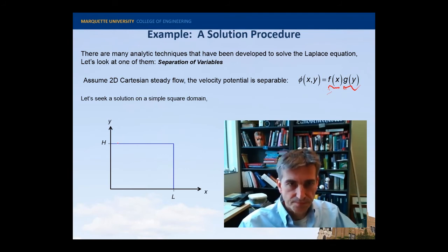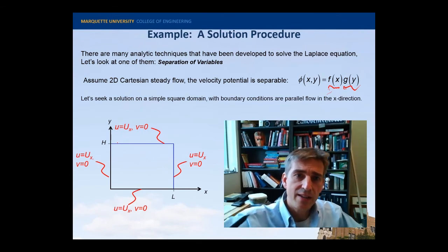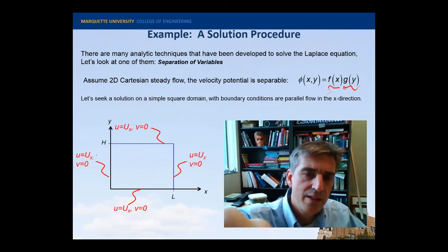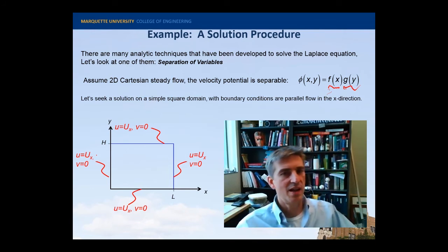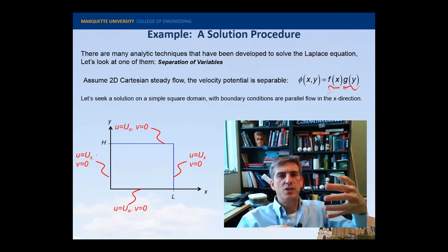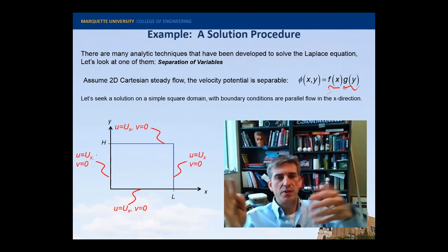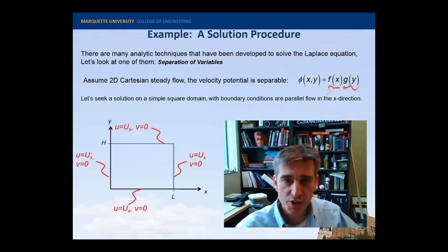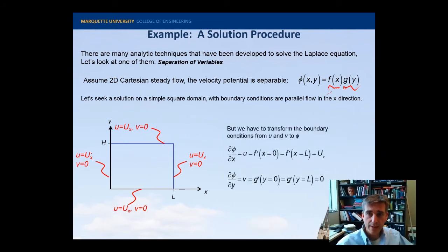All right. So the boundary conditions that we're going to specify are that the x direction of velocity everywhere on the boundary is constant, and it's this big U sub x, and then everywhere on the boundary the y direction velocity is 0. So really this is a horizontal flow, right? We're imposing just that we have a constant flow field across the domain. So it's a very simple problem, but it illustrates all of the key features.